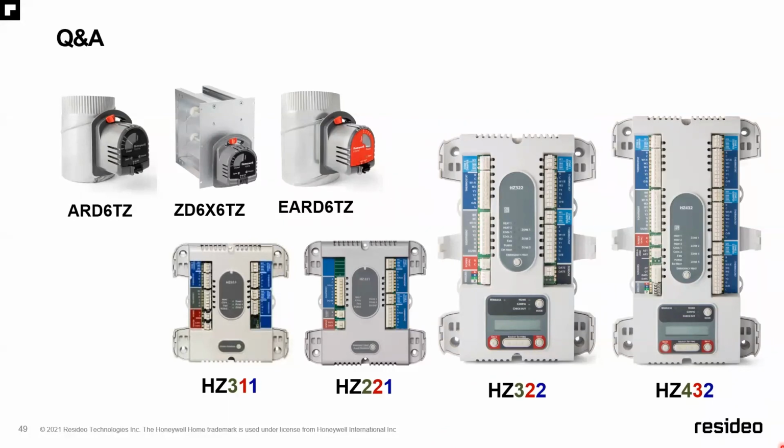When only one zone is calling and the fan is running in slow speed, do you have any problems with coil freezing, short cycling the compressor, or heat exchanger short cycling?